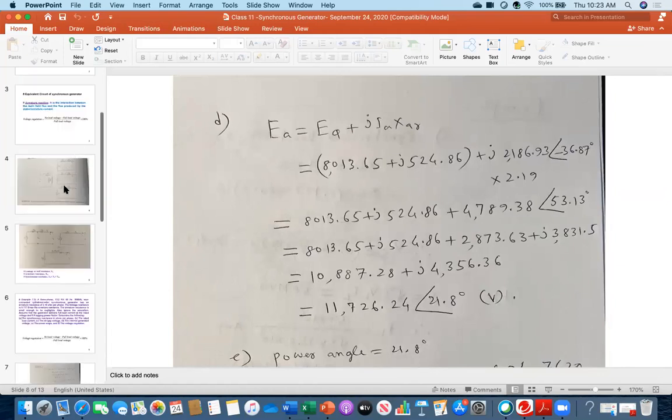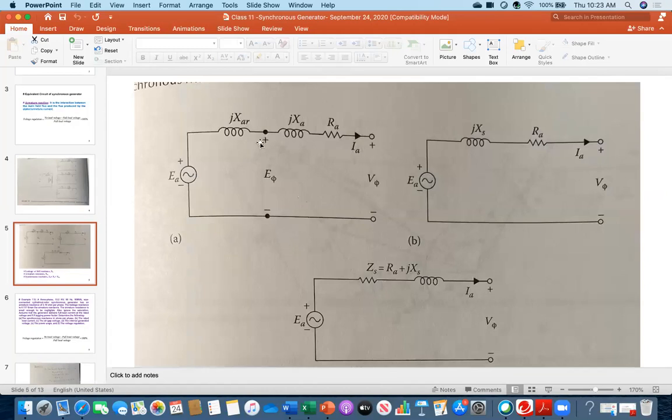So therefore, key is that you just remember this one. Everybody remember this diagram and just remember the meaning of the symbols, then you will be fine. Once again, this is terminal voltage, air gap voltage, internal generated voltage. So when you are calculating voltage regulation, you need to know this one, EI, which will be the no load voltage. Because when there is no load connected, IA is 0, meaning there is no drop. So only this voltage is available, which is no load voltage.